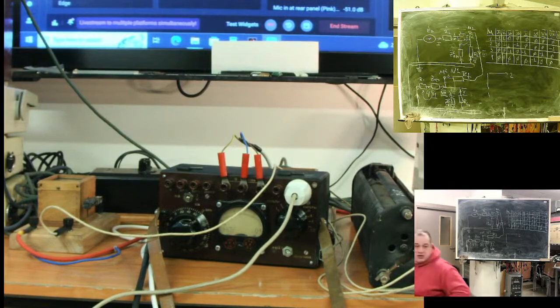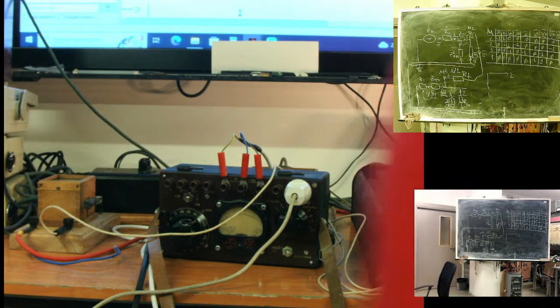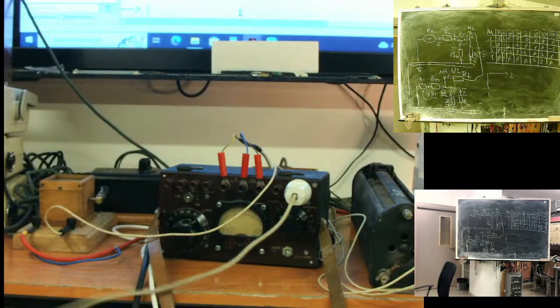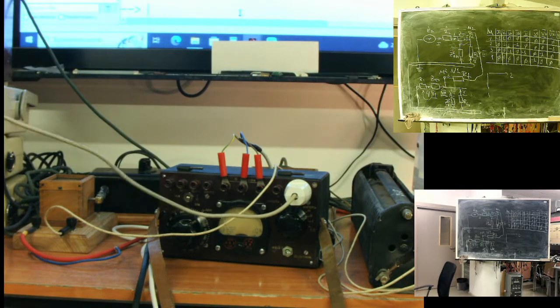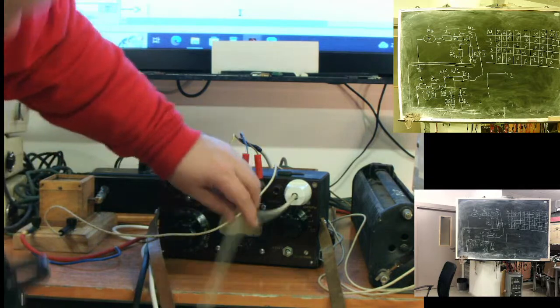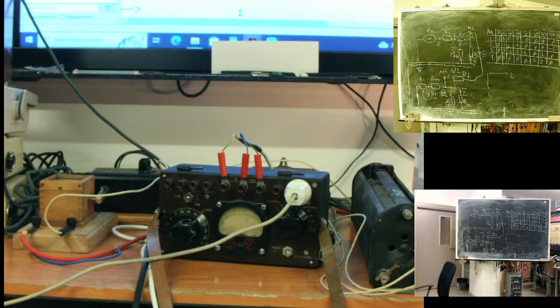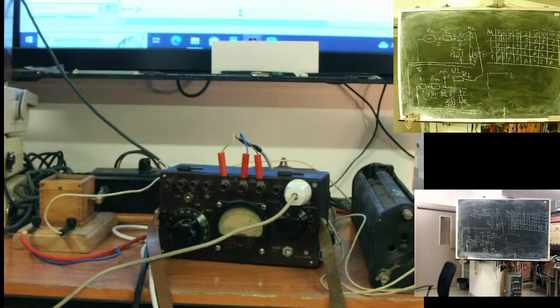Yeah, I will measure with my clamp. Let's see what we got. A phase 3.8. Set for 5 amps. A phase, where are you? Here, A phase flowing 4 amps.